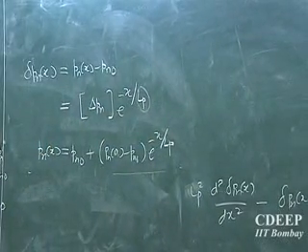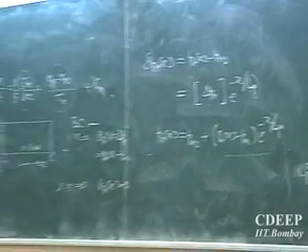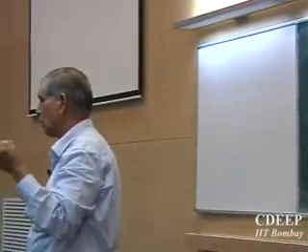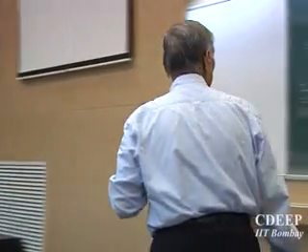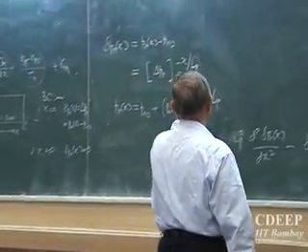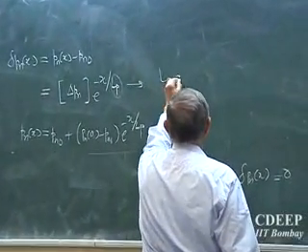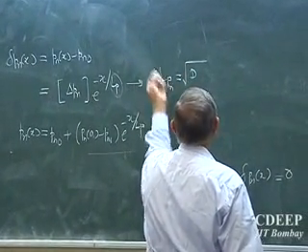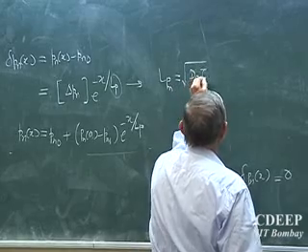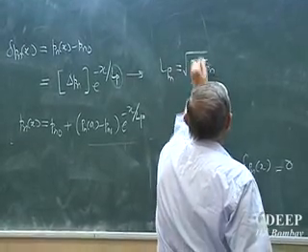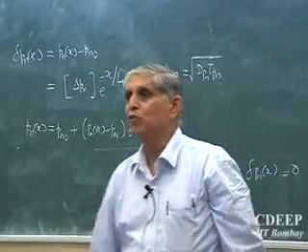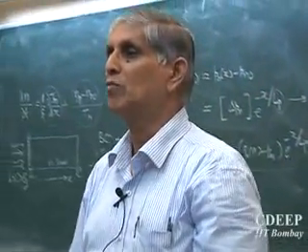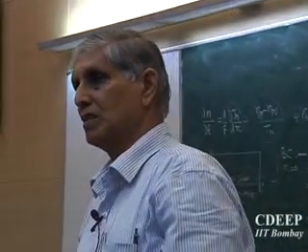The diffusion length. Dp tau p is Lp square. I am taking care of tau p, and I am taking care of diffusion in one term which is called diffusion length. So Lp is one of the major parameters in our device design, which is essentially, as I say, for the minority carrier. This term is going to decide therefore where we will reach the equilibrium or will not reach the equilibrium. Is that clear?